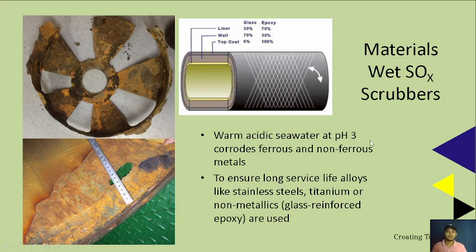Okay, so materials for wet SOx scrubbers. Usually the warm acidic seawater at pH 3 corrodes ferrous and non-ferrous metal. To ensure long service life, alloys like stainless steels, titanium, or non-metallics such as glass reinforced epoxy are used in our scrubbers.